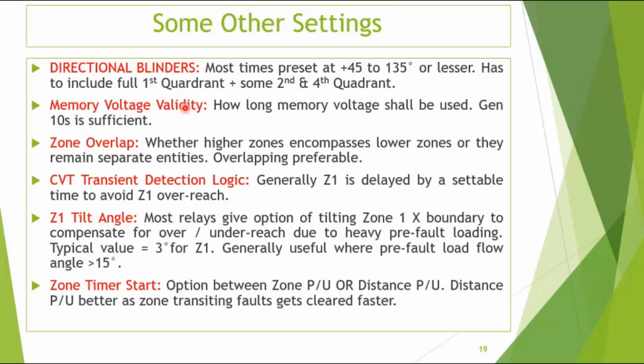Memory voltage validity. This is a newer relay concept, the concept of memory voltage. Nowadays we have memory voltage used to understand directionality. Now understand one thing, memory voltage is not used to understand the impedance of the fault, otherwise it will always have 100% impedance. If I use memory voltage, I have to use the faulted voltage.